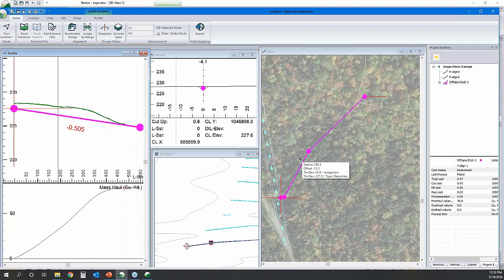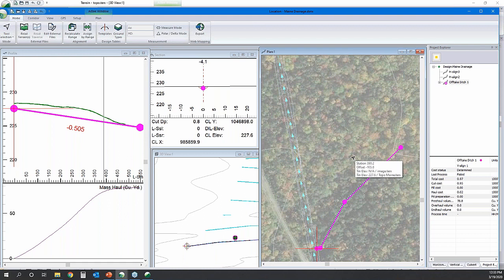So it might be worthwhile if you have the opportunity to put a mini excavator in there. You can ditch it away and keep your road prism nice and solid rather than having to import better material so it's free draining. Yeah, that's kind of the gist of this.